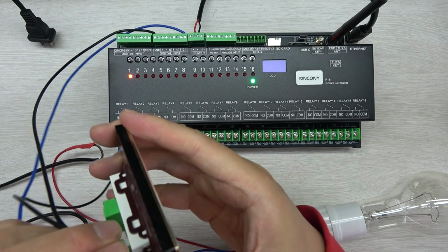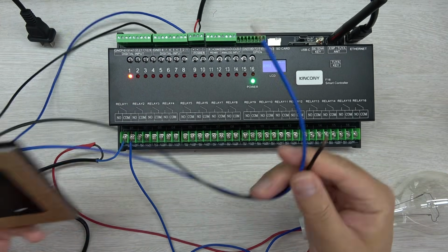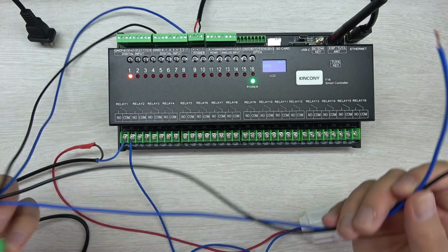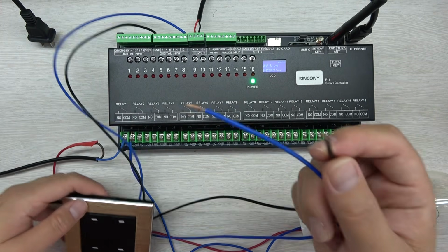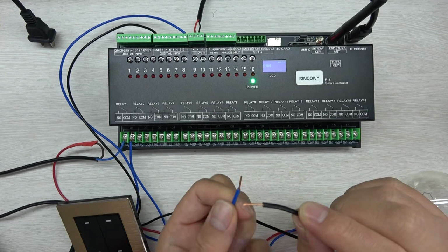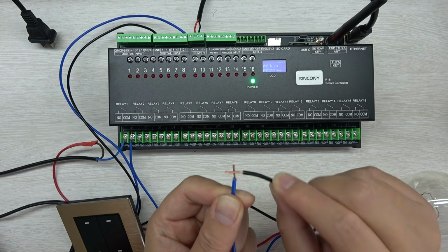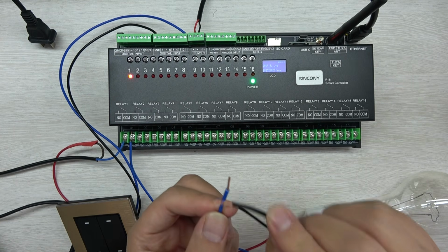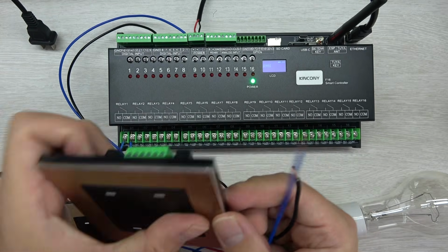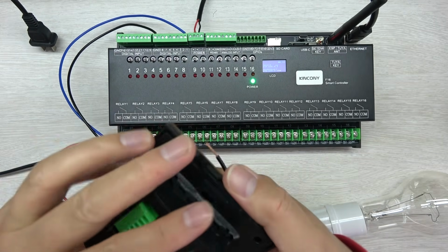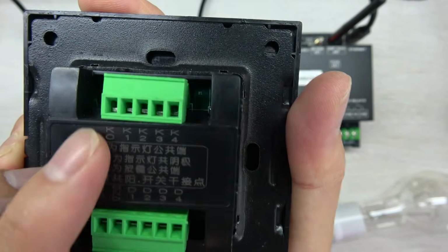Okay, and back to this. Now I will have this external cable, and you can see this is K1. But you can see this is another cable, and you can see I just short it. That will turn on, off. So it is just a very easy direct contact signal for on and off toggling of this relay. So you can connect with many different switches. This time you can see I can just connect with K1 and KC, that is ground. Just K1 and KC ground.